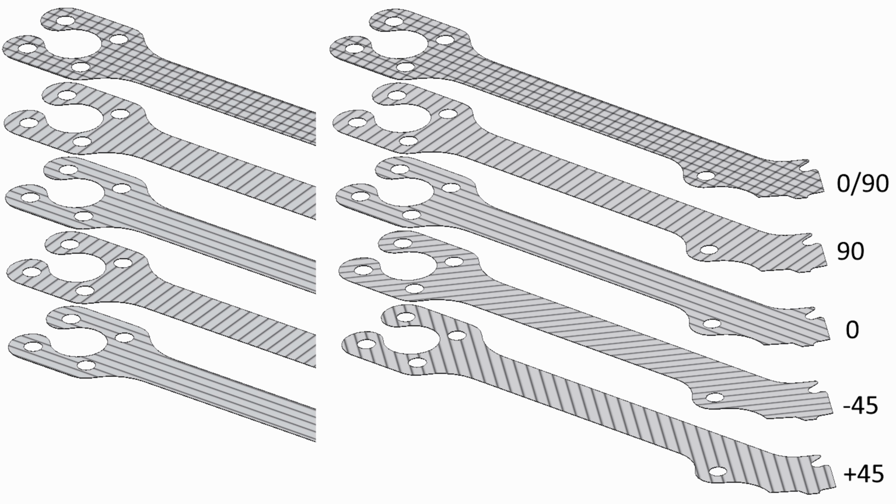Another way to do this is, instead of going 0 degrees and 90 degrees, you can go 0, 45, then 90, then back to 45, then back to 0. That takes fibers away from the length direction going straight down the arm and lends them to the 45-degree direction, which may or may not help with the torsional strain on the arm. But it does weaken the arm down its length. So it may break easier in the compression-tension direction, but it will hold up better, hopefully, in the torsional direction. Is that right? Yeah, exactly.